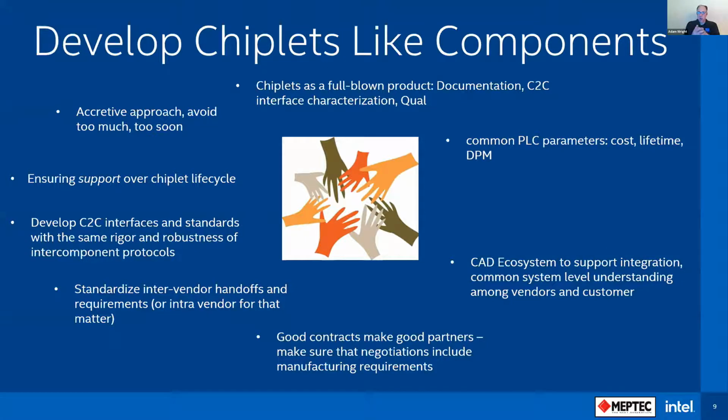We need to define what our common product lifecycle parameters are: cost, lifetime, DPM. We need to think about that. Again, FPGAs have a long life cycle, and we need our tiles to think about that. Because again, a good example of that is HBM. Our life cycles are off from the DRAM stacks. So oftentimes we have to think about, hey, how do we requal a stack to continue delivering the product? Again, it's fine, but it's better to know ahead of time.